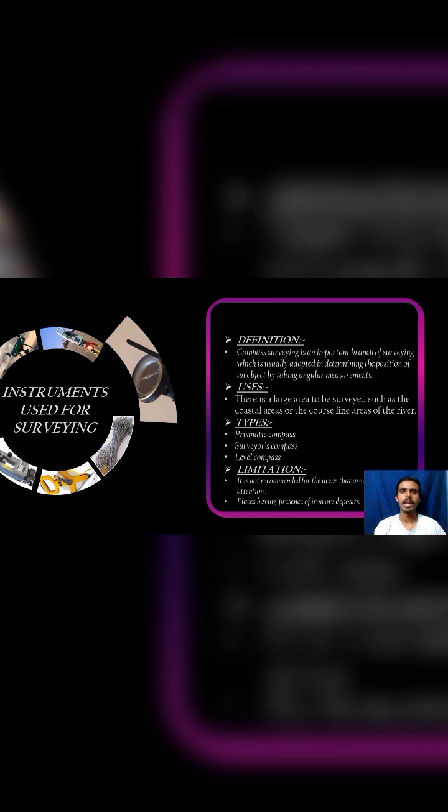The next instrument is compass. Compass surveying is an important branch of surveying which is usually adopted in determining the position of an object by taking angular measurement. These are used to measure large areas, that are coastal areas or the coastline areas of the river. Types of compass: prismatic compass, surveyor compass, level compass. Limitations: places having iron ore deposition are avoided as it might provide deflection and error might occur.